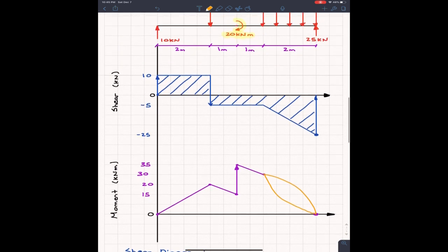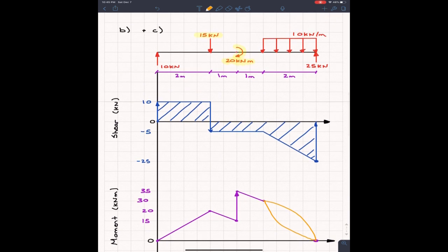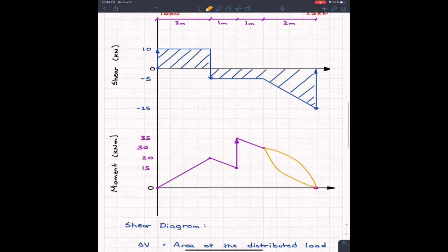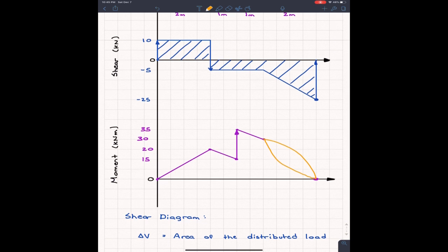So it's the same thing for the shear and the distributed load. Remember, I said that the slope at x equals 4, well, that's going to be the distributed load at that point, which was 10. At the point at x equals 6, well, that's going to be the distributed load at that point, which was still 10. That's how I knew it was linear across, is because the slope stayed 10 throughout the whole time. However, when we start looking at the shear now, the value of shear changes between these 2 points.